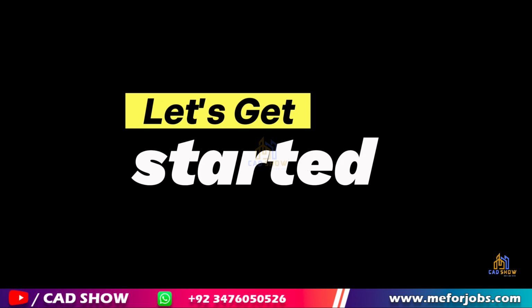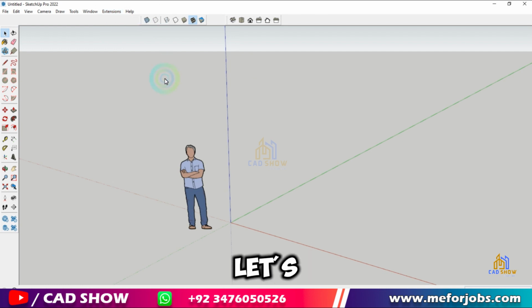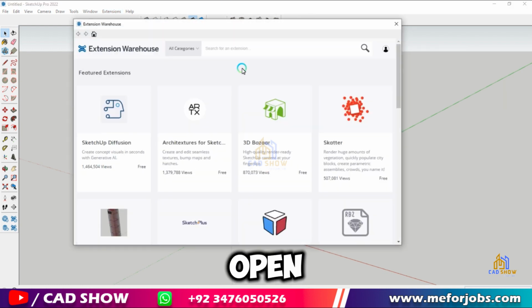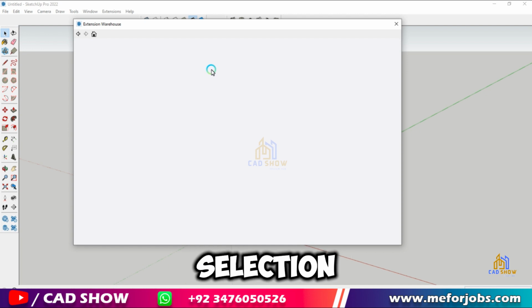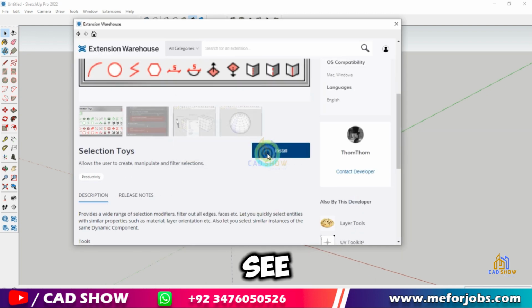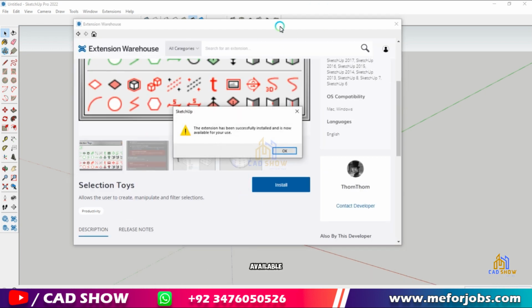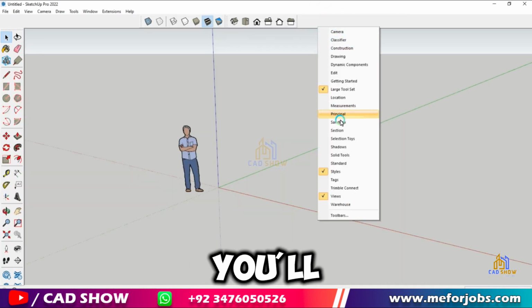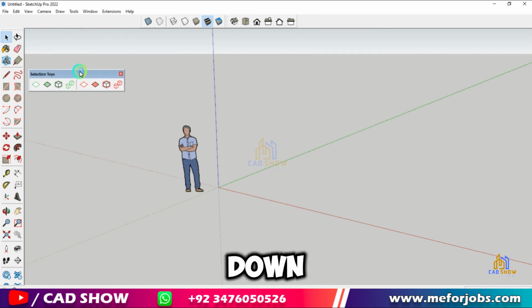Let's get started. Installing Selection Toys. First things, let's install the plugin. Open SketchUp and go to the extension warehouse. Search for Selection Toys by ThomThom and click on Install. Once installed, you'll notice a new toolbar with several icons representing the various selection tools available. Let's break down these features one by one.